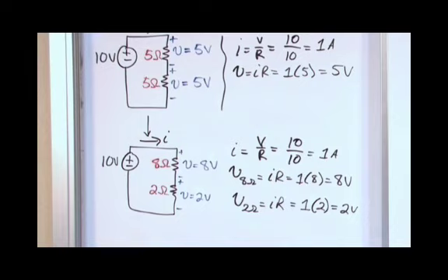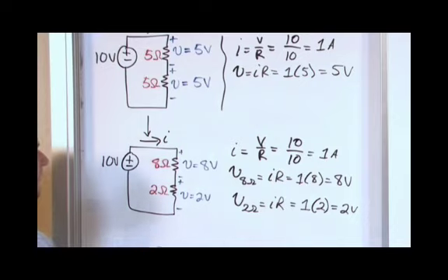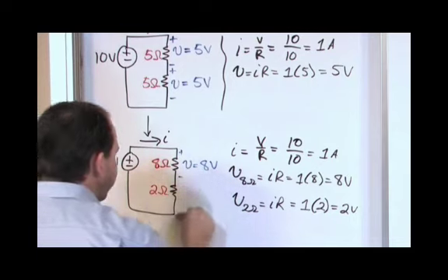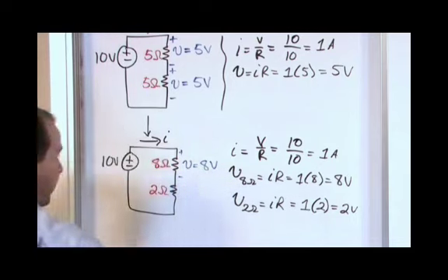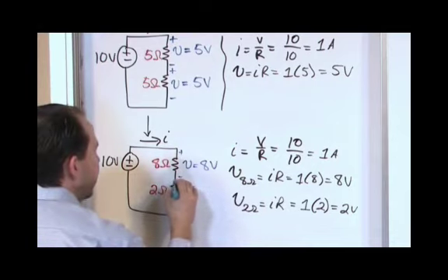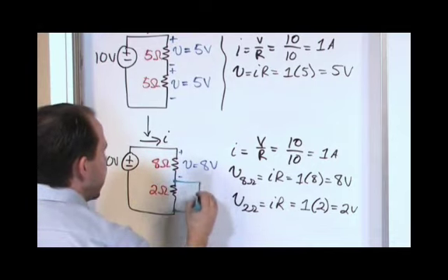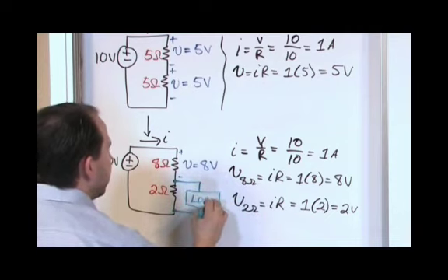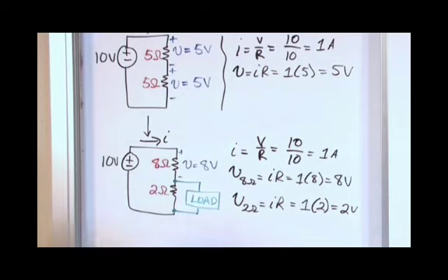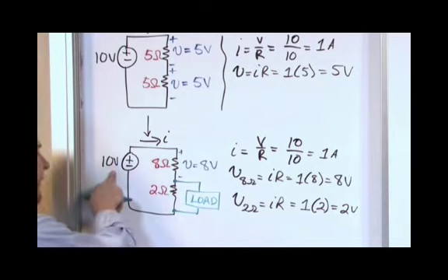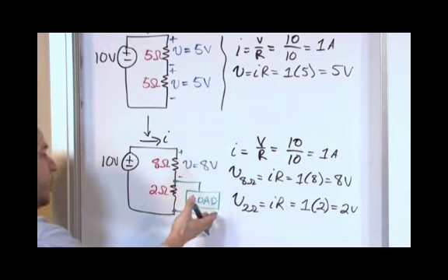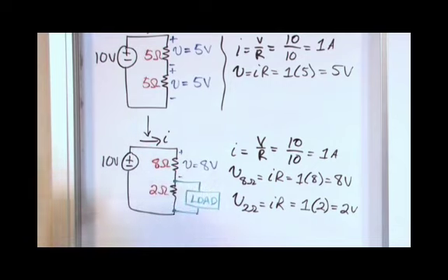All right, so again, maybe my circuit that I'm building in this particular case only needs 2 volts. Maybe it only operates at 2 volts, right? So if that's true, then I would connect something here, and I would hook up what I'm calling my load. This could be a light bulb. This could be some computer chip. It could be anything I want. But if I only have a 10 volt source available, but I really need 2 volts to accommodate my load, then I'm going to end up hooking it up like this.